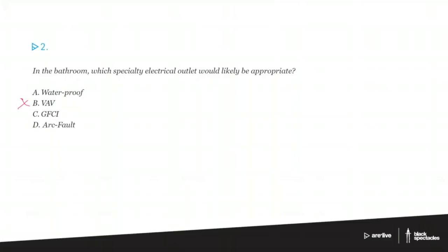And so the arc faults do a very serious job. But like I said, there's been a pushback about whether they're actually effective in saving any lives or saving fires. So it's a bit up in the air. It's hard to know how it would show up on the exam, but it is a real and potentially quite important electrical device that you should know about. But that's not the issue in a bathroom. I suppose it could be an issue in a bathroom, just like it could be anywhere, but much more likely a bathroom issue is going to be about water. So that leaves us with waterproof and GFCI.